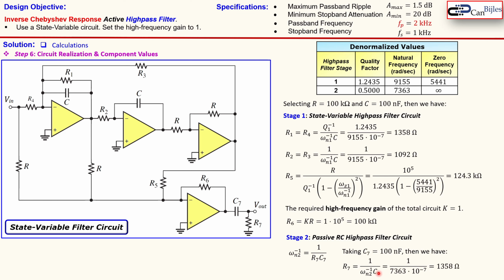Let's also calculate the cutoff frequency for our design. That is calculated using this formula for the high pass filter. You see here the stop band frequency, the cosh, which is the hyperbolic function, the inverse of that one, the epsilon s, which is the scaled value from the A minimum, and our filter order. Now when you substitute the values, here you get 1000 times the coefficients, you get almost 1.54 kilohertz.